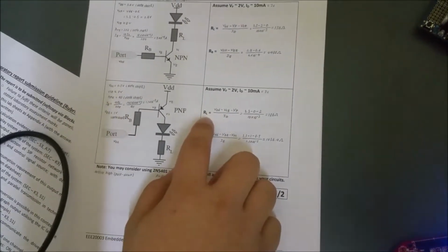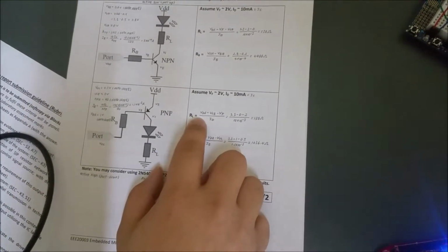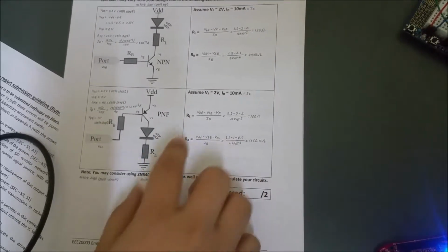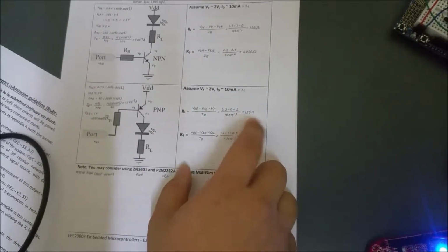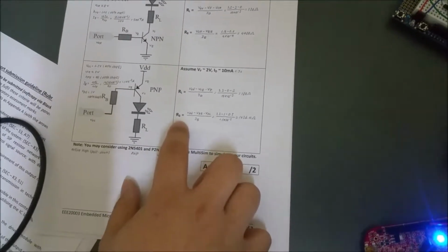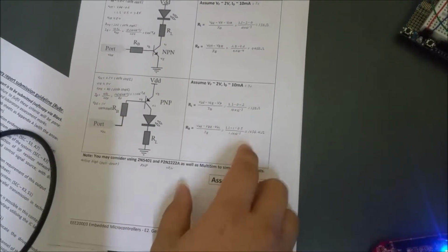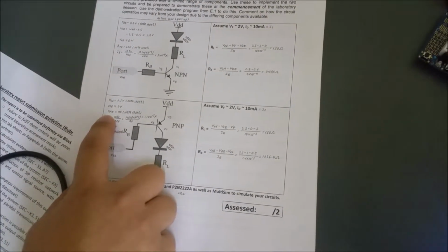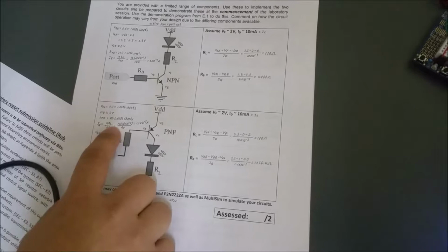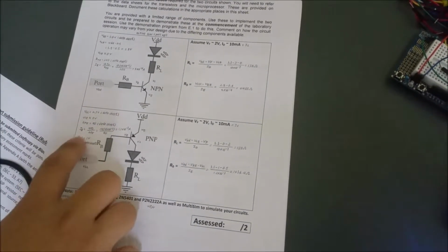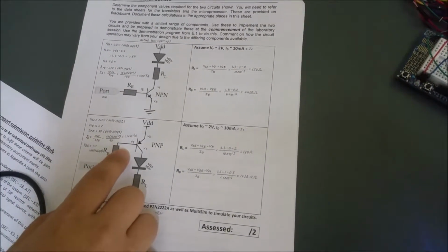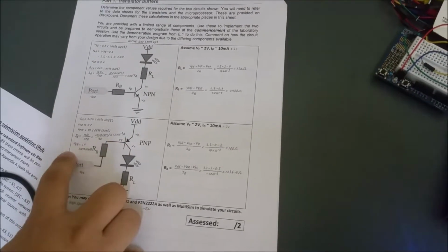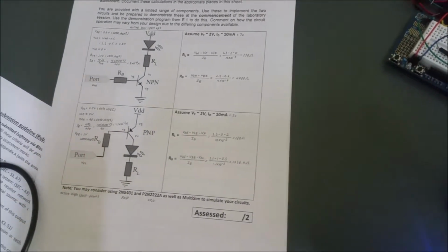So moving on, we will have our load resistor, which is calculated to be 130 ohms, where our RB is equal to 1636.4 ohms. So moving back here, based on the datasheet, we have our HFE equal to 90, with our IB equal to 1.1 times 10 to the power of negative 3 ampere, and our VBE according to the datasheet of 1 volt.